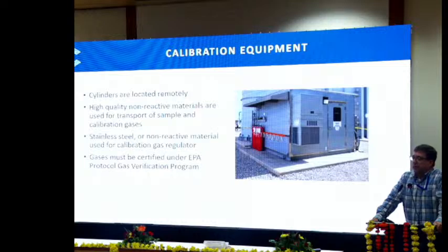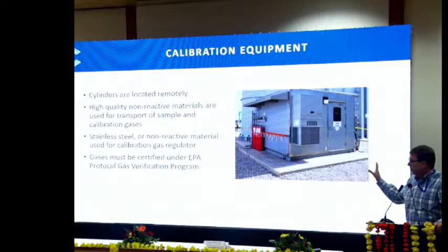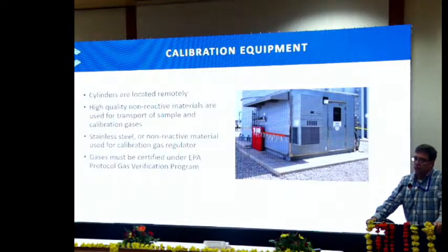Stainless steel or non-reactive materials are used for the calibration gas regulators. This is especially important with gases that are very reactive. You can have silica-coated wetted surfaces to help minimize corrosion. Typically with your normal gases, they're stainless steel or brass.